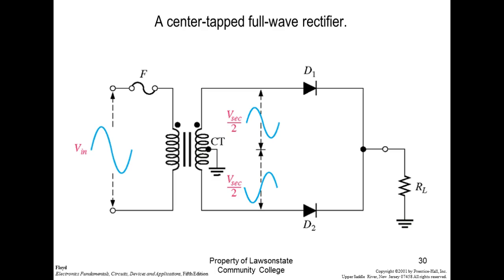So this is what we call a center tap transformer. Don't pay any attention to the dots. It's on the top. Normally, a lot of times they'll wind the windings right on top of each other. It is what we call an E-core transformer. Now what this causes is that when this input's going positive, the current's going out here, it's going to be coming in there. So over here, the actual secondary would be 180 degrees out of phase, which in power supplies makes no difference, right?